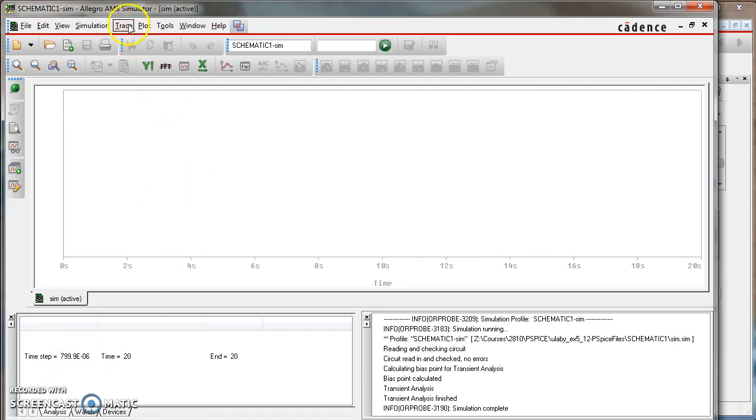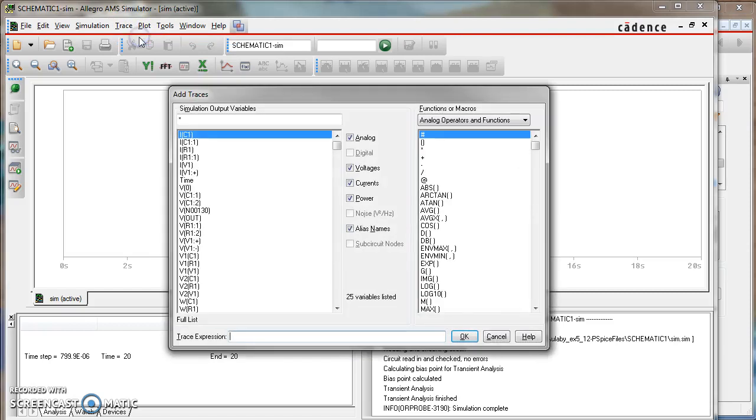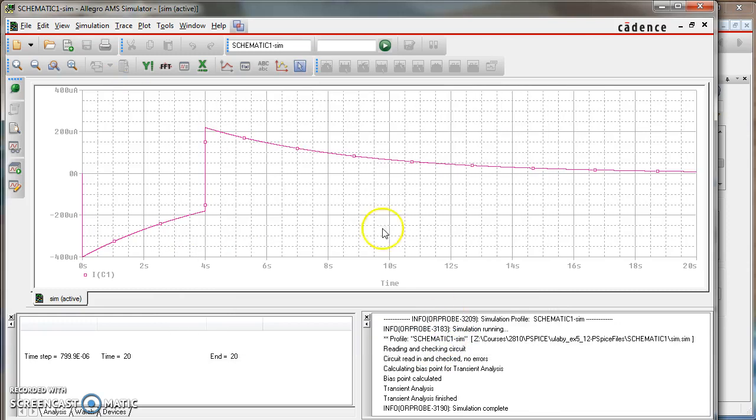Okay, I went ahead and deleted that trace and started over. I want to show you a couple things here real fast. So we have these different currents here. Now there is just one loop current going through, but it's obvious that which one we choose, we're looking at a direction of current. So what I want to look at here is the current going into the capacitor. See that if I select it, it's showing the current that is leaving the capacitor is negative.